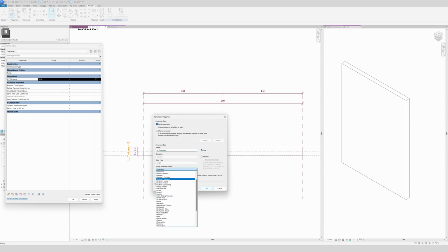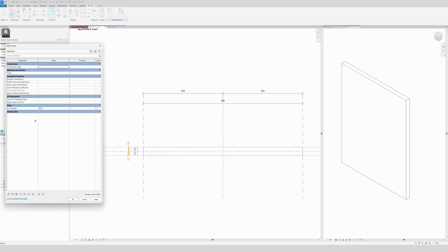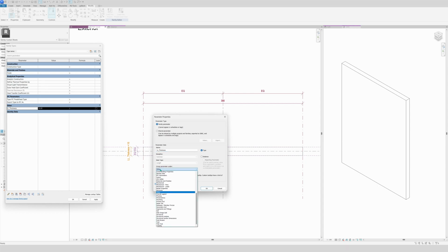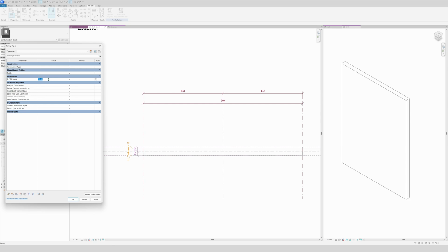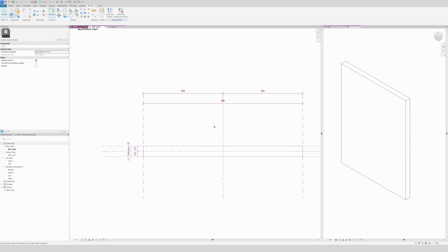You can just adjust it right now if you already made the parameter, like with other. If you click OK, see the group is now in other, but we want to adjust it to dimensions, voila, and it appears right here. So we will change the thickness to 20 maybe. Then you click the tab key, voila, click apply, and OK. You see the extrusion is moving with it, so the family works just fine. We will click OK, and voila, that's our first thing that we have.